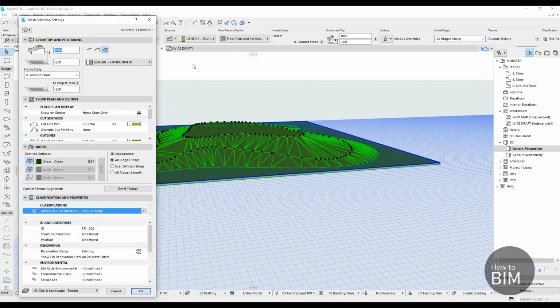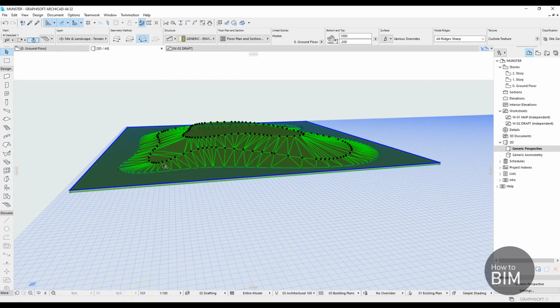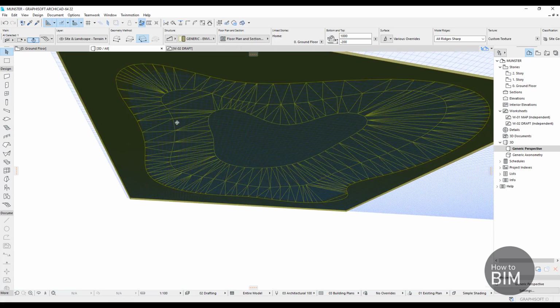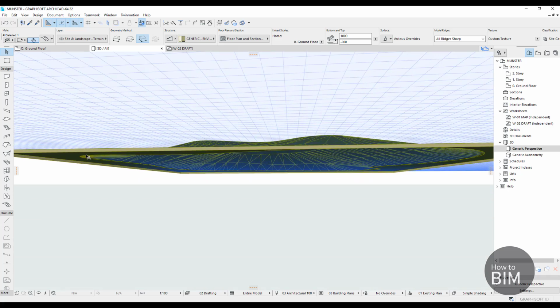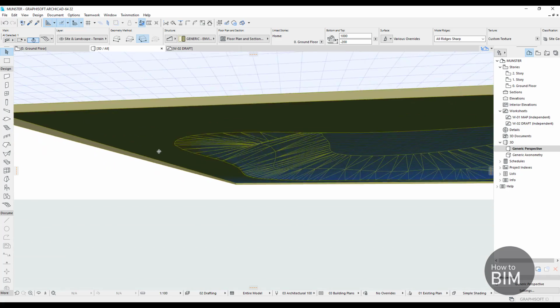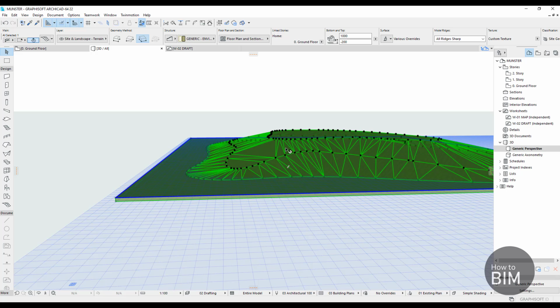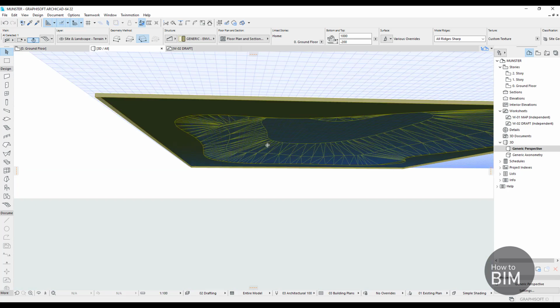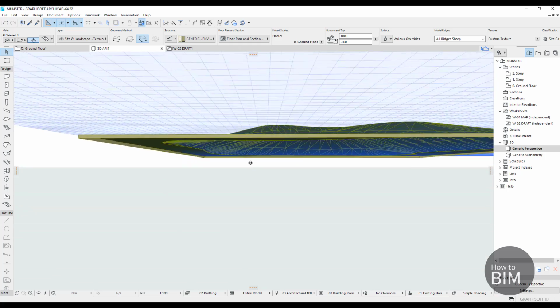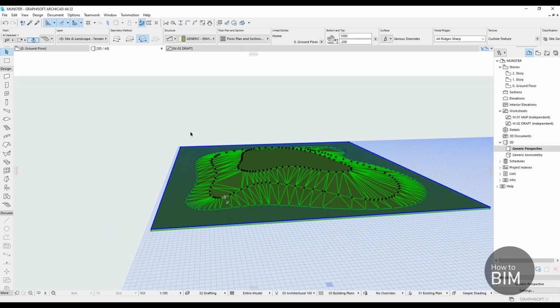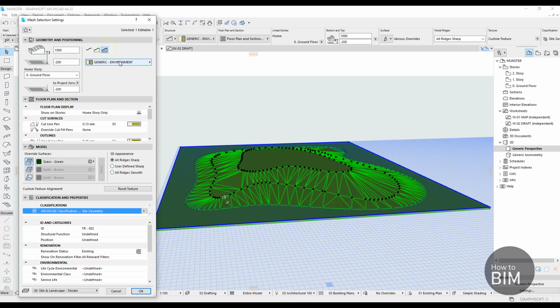And we have one more option, and that is this one. It looks like nothing actually happens, but no, you can see already the thickness of the slab is everywhere the same. So that means that if I pull these points up to create the hill, then also the slab is gonna pull up in there, so that it will create this hole inside. Sometimes you find this useful, for example, maybe for some foundations or so. But we will leave this option open.